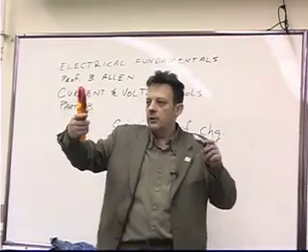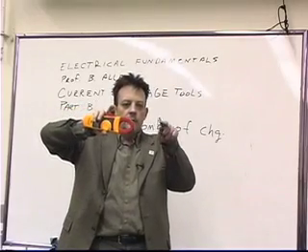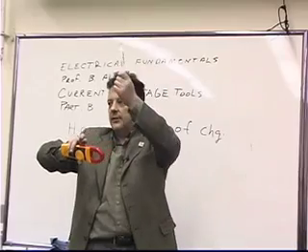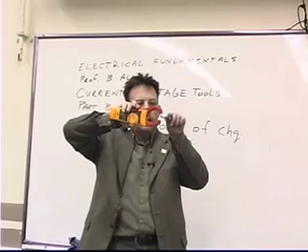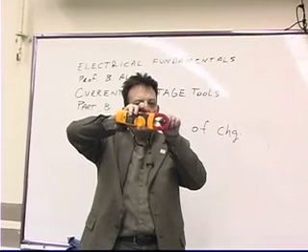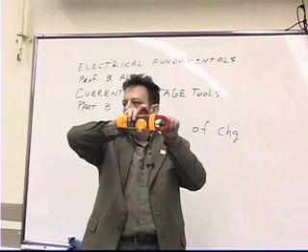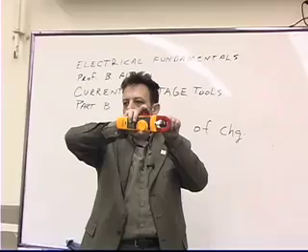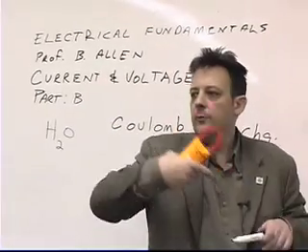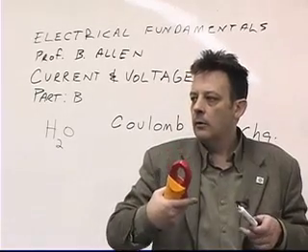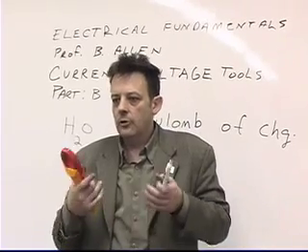Because really what you're doing is you're taking this meter, and you've got this wire. Just pretend like this pin is a wire. You've got this wire, and you're opening up this meter, and you're putting it over this wire, and you're closing it, but the wire isn't even touching the meter. So how's it measuring anything? Well, the way it's measuring something is because there's a magnetic field around the wire. And it uses a phenomenon called the Hall effect to measure the current.